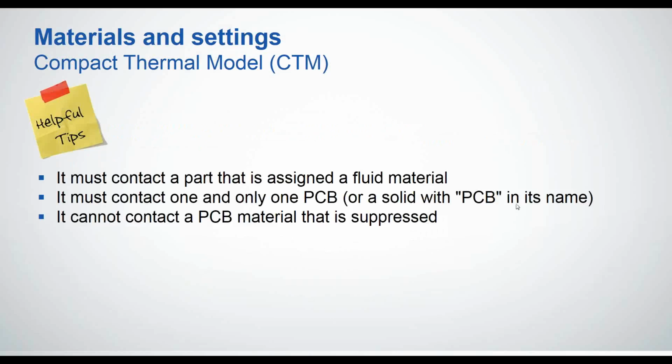Some helpful tips for the modeling of your CTM are the following. It must contact a part that is assigned to a fluid material. You have to make sure that you have this condition, and it must contact one and only one PCB, or you will get an error message saying that you have more than one PCB, or a solid with PCB in its name.